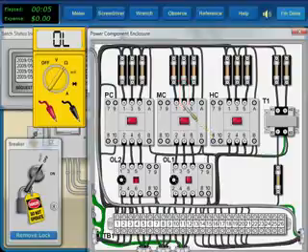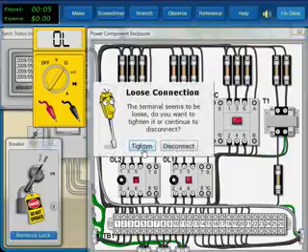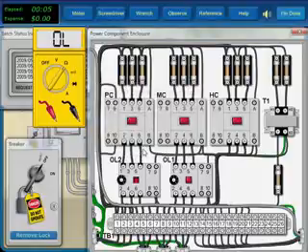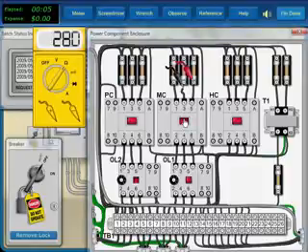We begin to disconnect the wire, but find a loose terminal. Since this fits the symptoms, we tighten the terminal to repair the circuit. To verify the repairs, we test the full path through the motor. The low resistance reading indicates the path is complete.